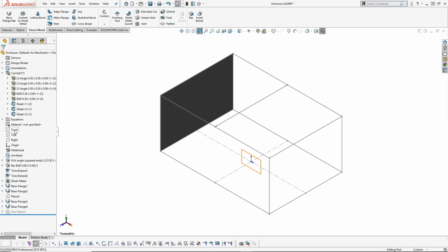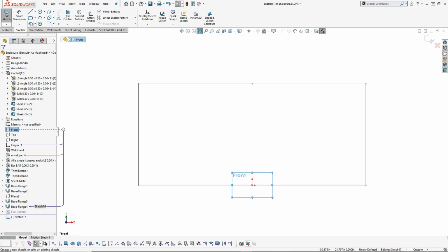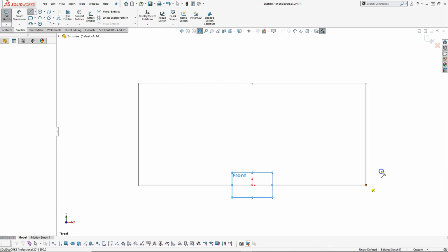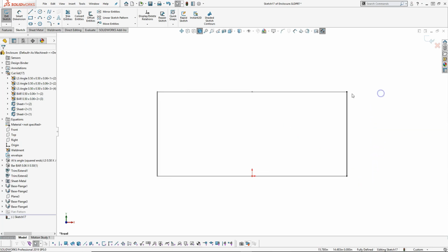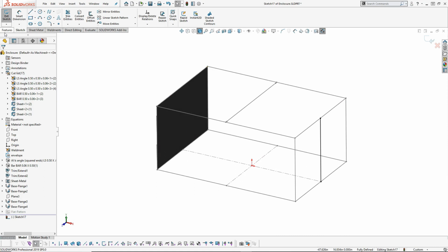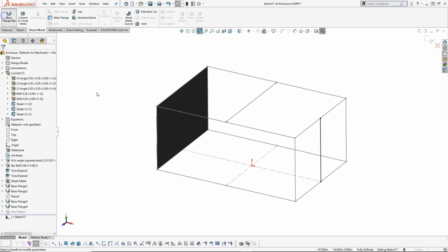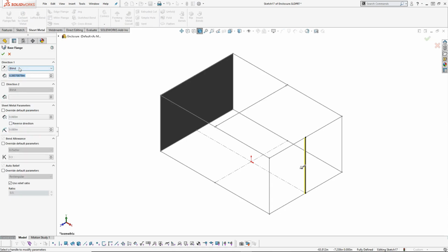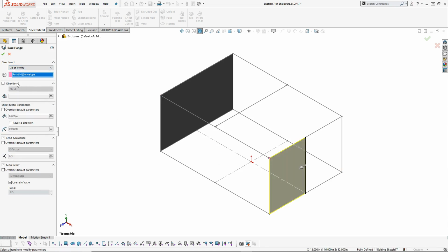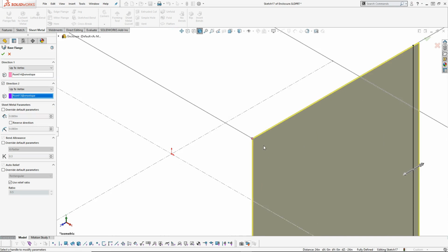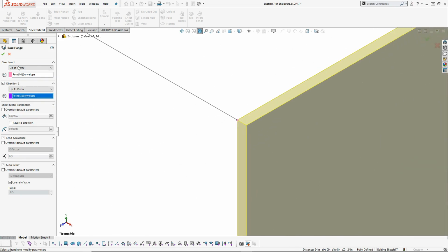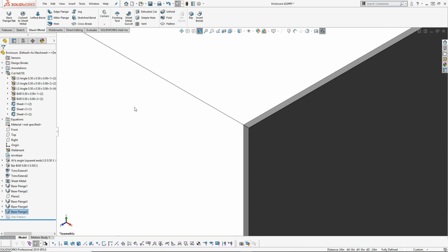Alright, and then the last one on the front plane again. Mainly for convenience, I don't know that I would have created the other planes automatically there, at least without some kind of good reason. So let's just stay on the planes that we're working with since they're operational. Up to vertex, and then direction 2, up to vertex, and then we'll check the side, so that is coming exterior. Alright, looks good.